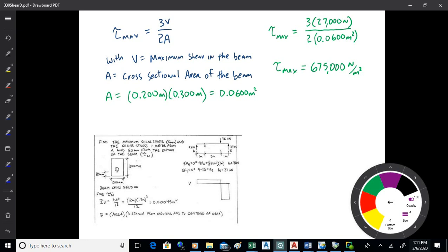So that's the last bit there. Quite a bit more than the shear that we found at C1. So if you're going to design that beam for shear, that's the value you'd use right there. So that's the deal with that.